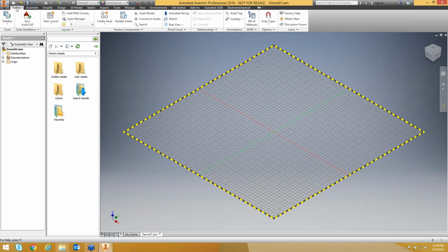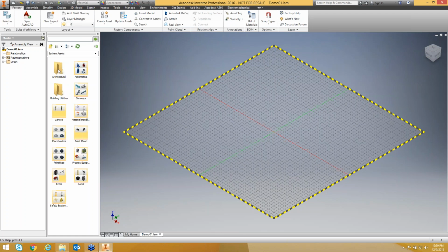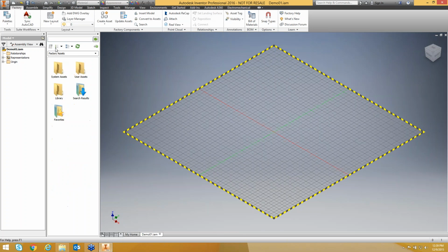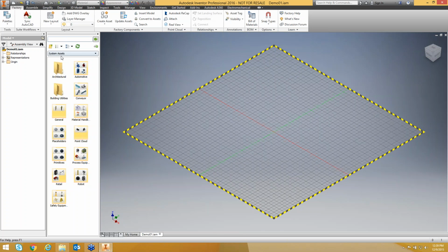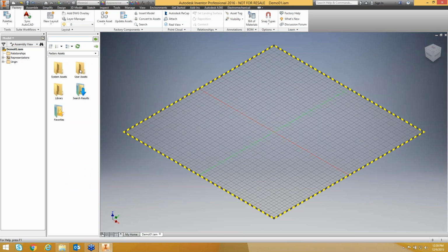Now, one thing specifically about building assets inside of Inventor. The assets are quick, easy things to grab and put inside of your layout. Over here in this section is your asset layouts. This comes out of the box for the most part. You have a suite here, or a layout, of different what they refer to as system assets. And this little blank area here represents your user custom developed ones.